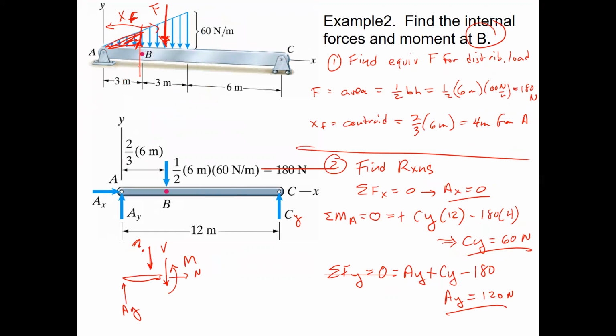Well, when you're doing moments, that may be referring to the line of action of a force. When you're trying to do the moment about some point P, and you have a force applied here, maybe going in this direction, that line of action, which my pen just graciously created for me right there, is anywhere you can do the moment calculation.